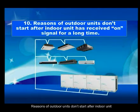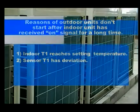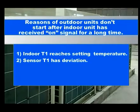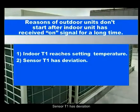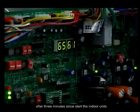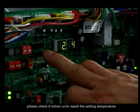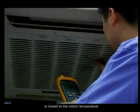Reasons why outdoor units don't start after the indoor unit has received the on signal for a long time. Indoor T1 reaches the setting temperature. Sensor T1 has deviation. Check the capacity requirement of the outdoor unit 3 minutes after starting the indoor units. If there is no capacity requirement, please check if the indoor units reach the setting temperature.